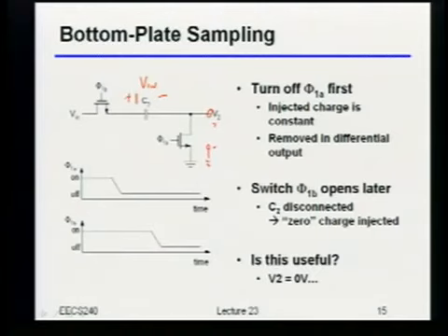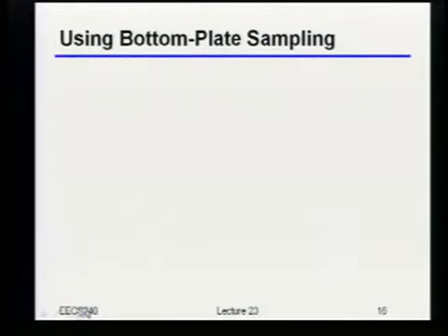Okay? So let's see how we can do that, and actually in a way that should be very, very familiar to you guys. In fact, I claim that that switched capacitor amplifier that I showed you guys a long, long time ago, you could actually modify it ever so slightly to do exactly this bottom plate sampling trick. Okay? So let's take a look at that.